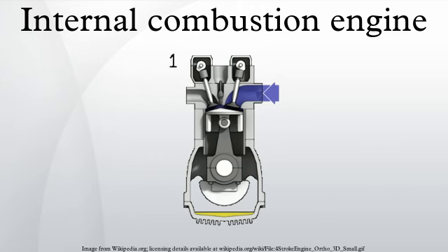4. Exhaust stroke. At the end of the power stroke, the exhaust valve opens. During this stroke, the piston starts its movement to the maximum volume position. The open exhaust valve allows the exhaust gases to escape the cylinder. At the end of this stroke, the exhaust valve closes, the inlet valve opens, and the sequence repeats in the next cycle. 4-stroke engines require 2 revolutions. Many engines overlap these steps in time. Turbine engines do all steps simultaneously at different parts of the engine.